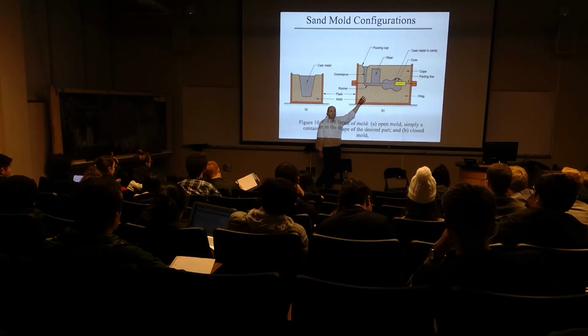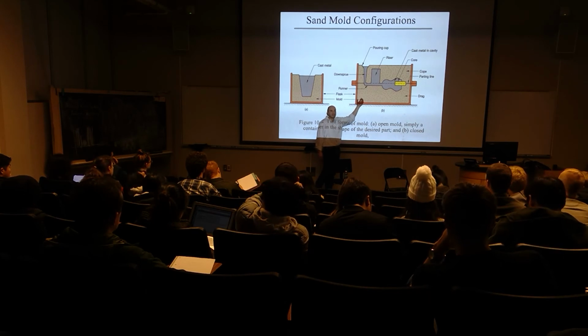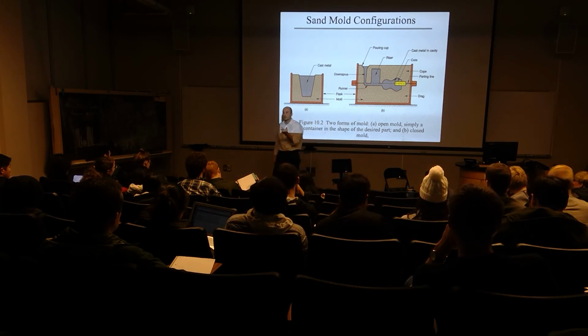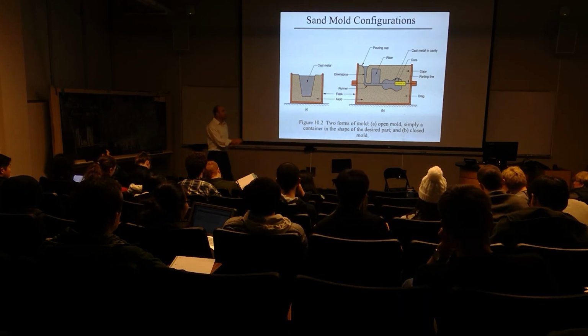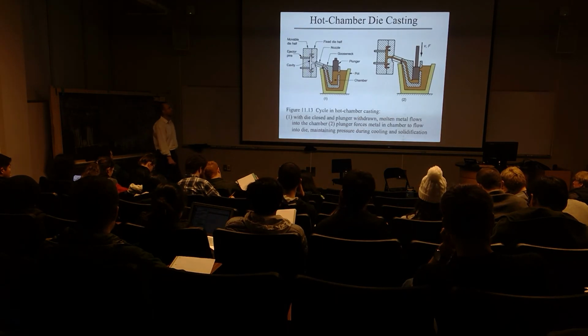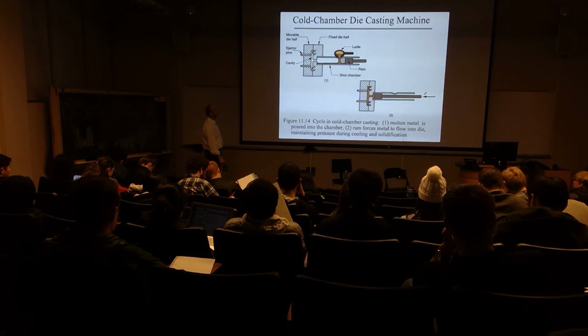It has much, much lower thermal conductivity. So it can't remove heat very fast. That influences grain growth. It influences grain orientations. And that means these two processes can have much different microstructure that's really important to the way that you might see those components fail.